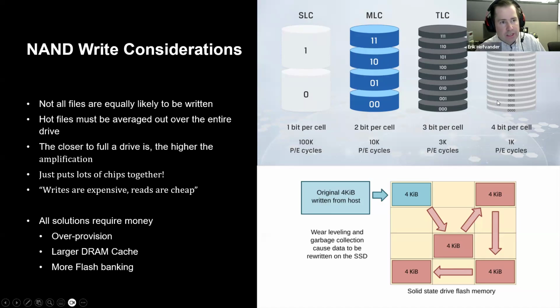If we're doing QLC, that means we have to have much more sensitivity. We have to be able to distinguish 16 states accurately from each other. So the difference here is much, much, much smaller than the difference here and here. You're getting further and further away from that binary. So in general, in NAND, write is very expensive and read is almost free. Reading doesn't cost us much.